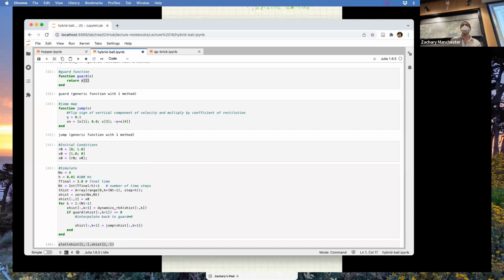So one of the things that can happen here is, if I do this, when does the ball actually come to rest? Never, right? In theory, the bounces get smaller and smaller, and they actually get higher and higher frequency, and they never actually get to 0. It's called Zeno's phenomenon, and it becomes a problem with these methods sometimes. And you'll find in a lot of the control work on this kind of stuff, you have to make assumptions about this. You have to basically say, I'm assuming that we don't have Zeno phenomena and a few other things. This can get weird.